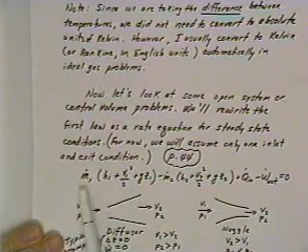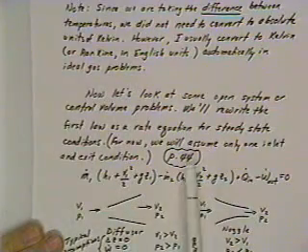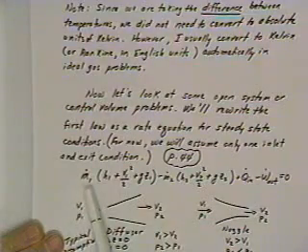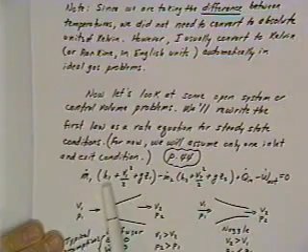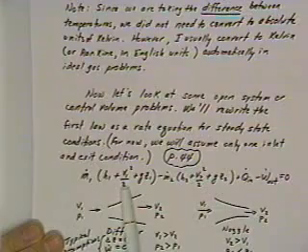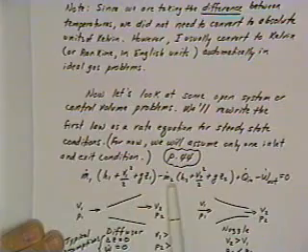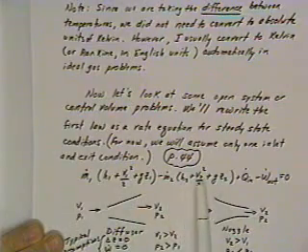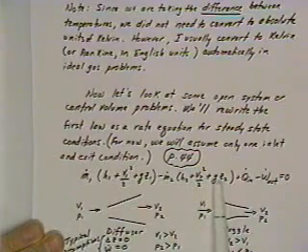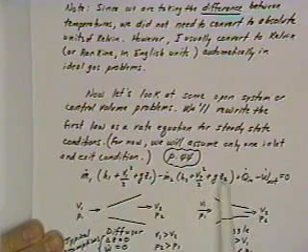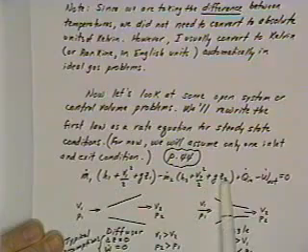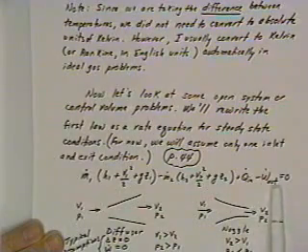So our first law that we had written as an open system or control volume approach from page 44 simplifies to m dot 1, which is the entering mass, multiplied by the enthalpy of 1, V1 squared over 2 is the kinetic energy term, g times Z is the potential energy term, minus m dot 2 times H2 plus V2 squared over 2 plus g times Z. That's the exiting enthalpy, kinetic energy, and potential energy term, plus Q dot in minus W dot out equals 0.